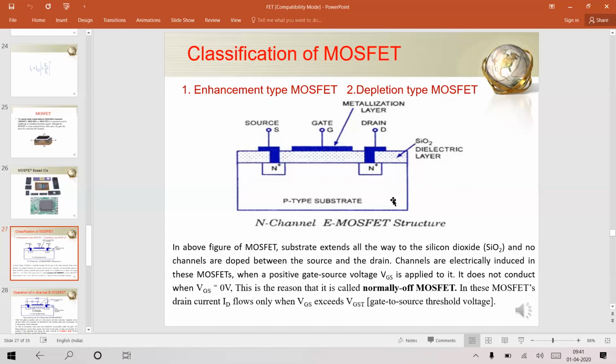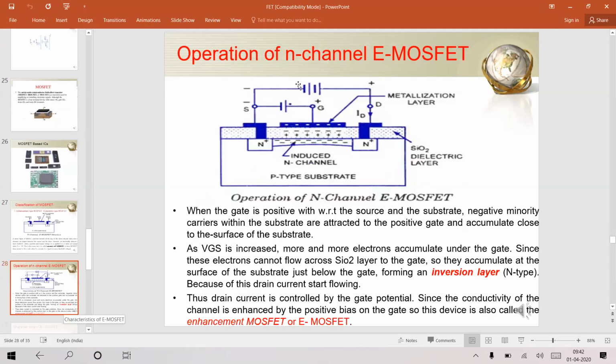In silicon devices, even in a diode, 0.7 V is the cut-in voltage of the device, we say. So once the input voltage applied exceeds the threshold voltage, you can say that the device starts conducting, right? Similarly, in this device also, there is a threshold voltage above which it starts conducting. That means the gate source voltage applied should exceed the threshold voltage, then it starts conducting. Let us see the next slide, you will get more clarity.